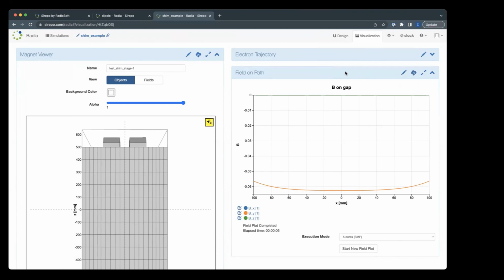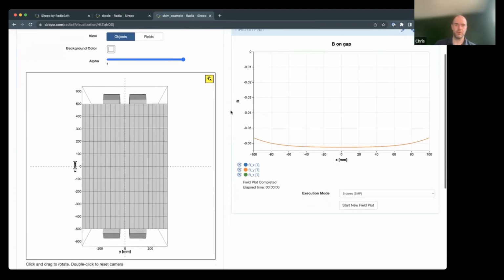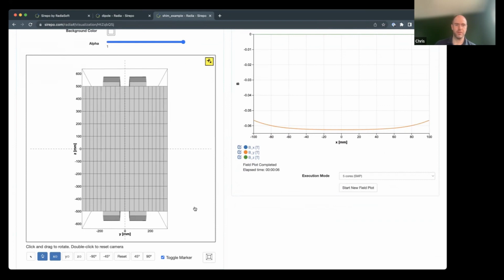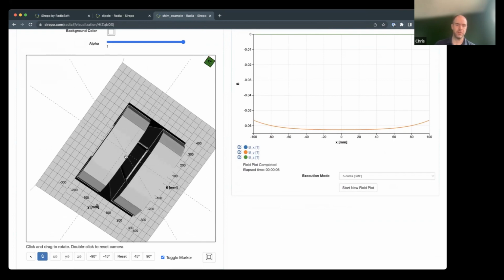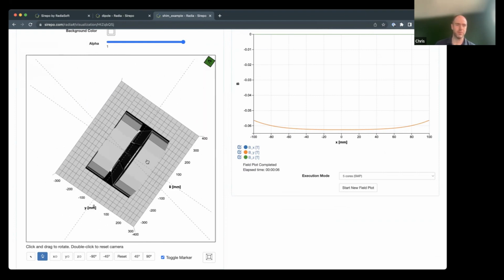Okay, thank you. Next question is, can we change the shape of segmentation to cylindrical? To cylindrical. I'm not quite sure how that would look. Generally, for most objects, you're going to end up just segmenting in cuts along the primary axes. And then for special cases, like the extruded objects, you do have this triangular segmentation that's set up. And that can be, I believe, applied to other objects. Not in this interface, but in general, Radia does have that capability to do that triangular segmentation.